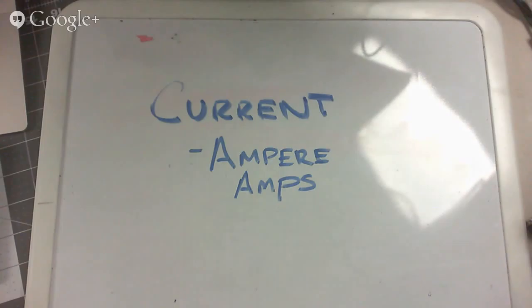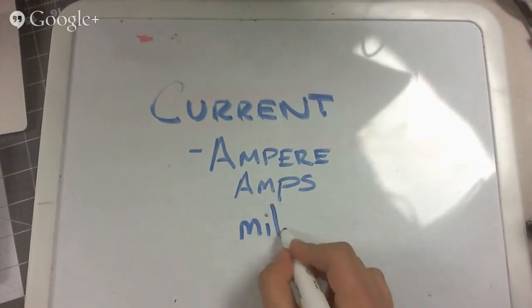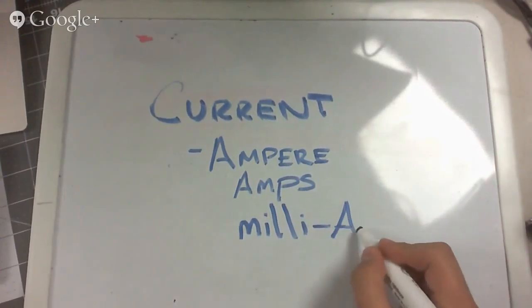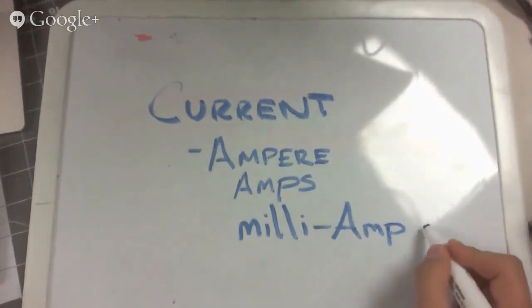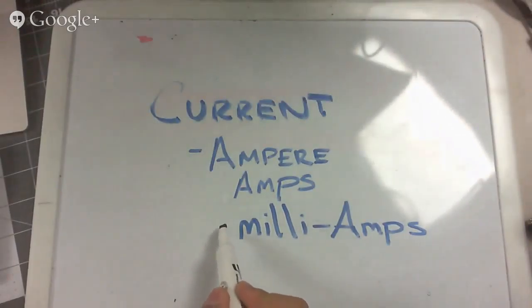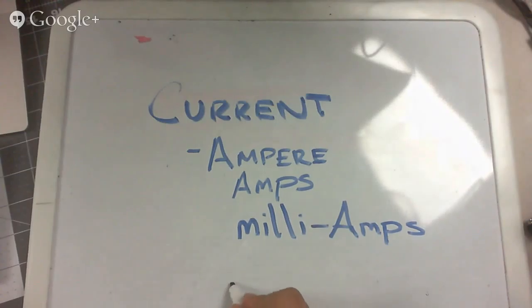And even with that, the kind of currents we're talking about, usually we're talking in the milliamps, which still under the right conditions is enough to stop your heart from beating. So, always, no matter what you're doing, even if you're not doing what's considered high voltage work, always be careful. And we'll talk about safety as we move along. That's usually also abbreviated mA.